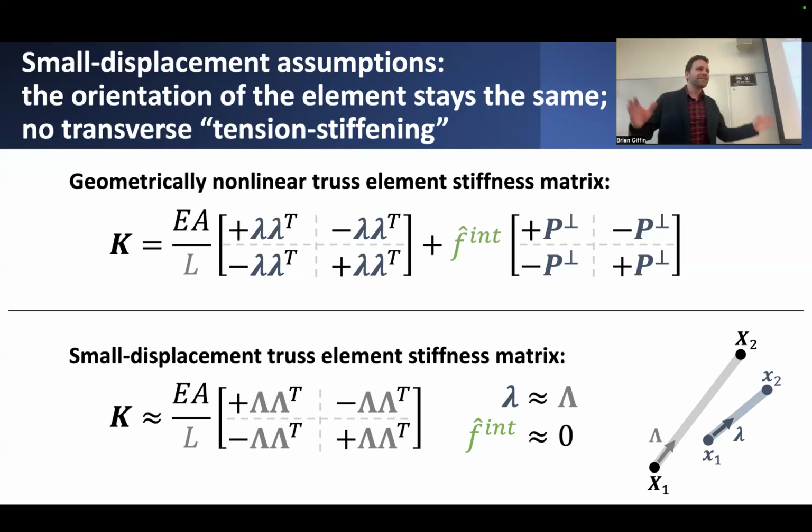And interior to all of these products would be gamma transpose times some small 2x2 matrix times gamma on the right-hand side. And that 2x2 matrix would look something like EA by L, and then a small 2x2 that involves +1, -1, -1, +1. You can think of this expression as encapsulating all of those different things compressed together, involving the orientation vectors expressed like so.